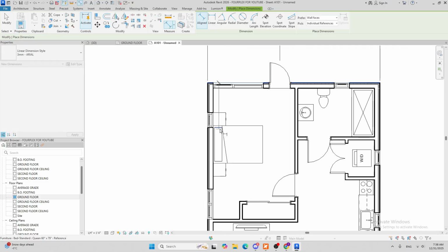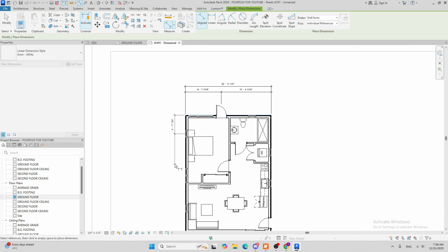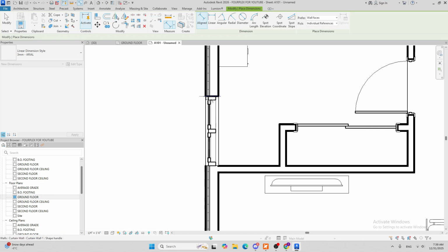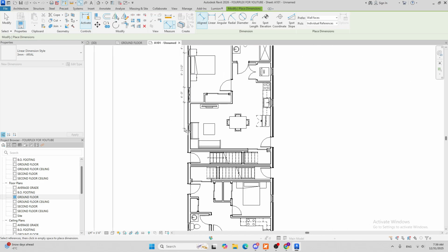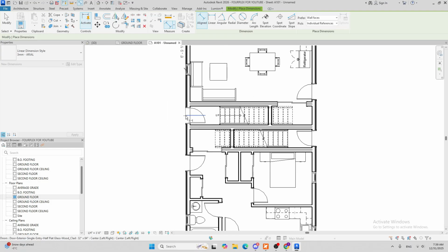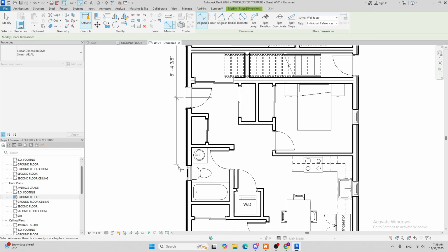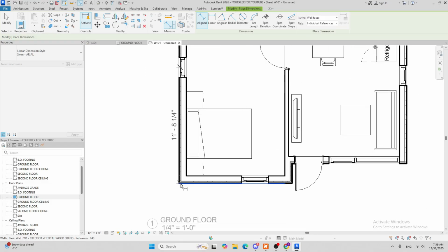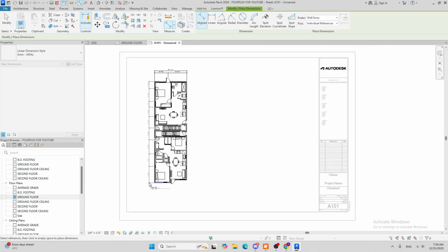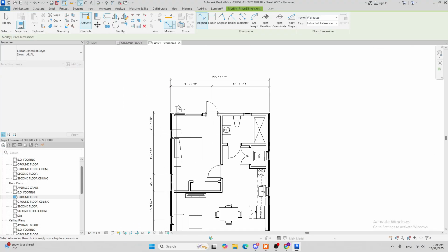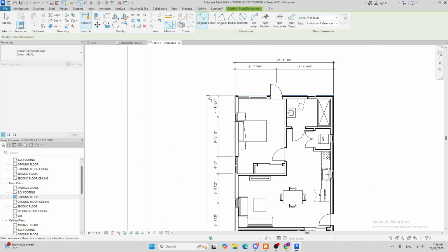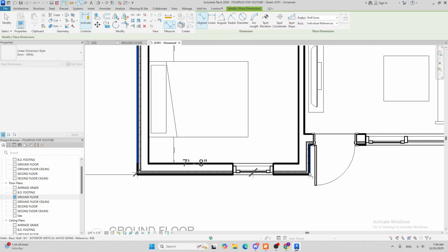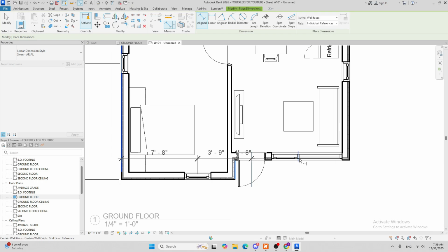And that's pretty much what you have to do for the dimension of the floor plan. So I'm gonna do the center line of the opening and to the edge of the wall, and I'll do 1 overall dimension. Yep, you can just click it and do your dimension.